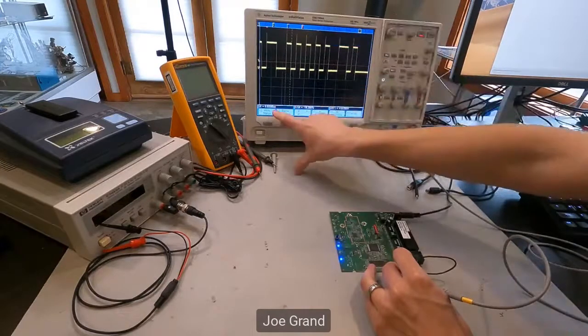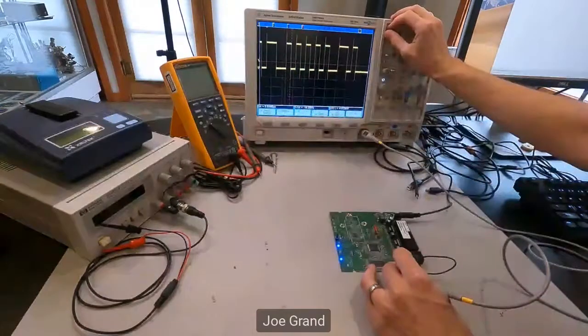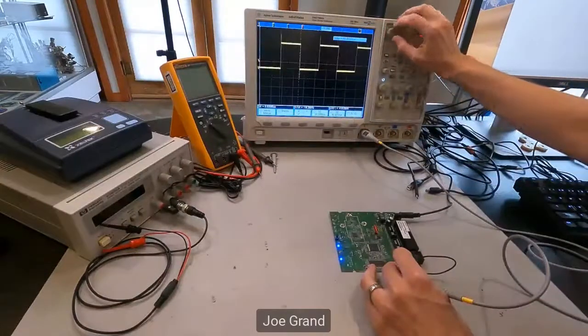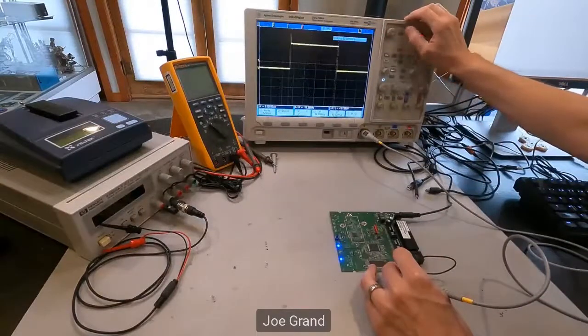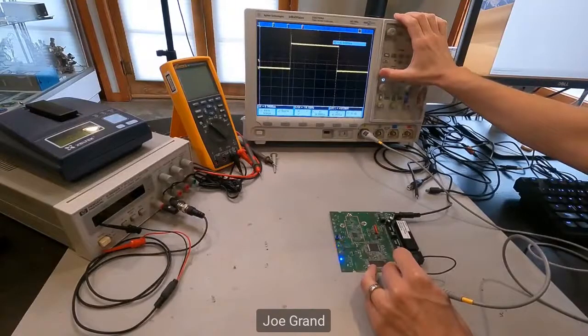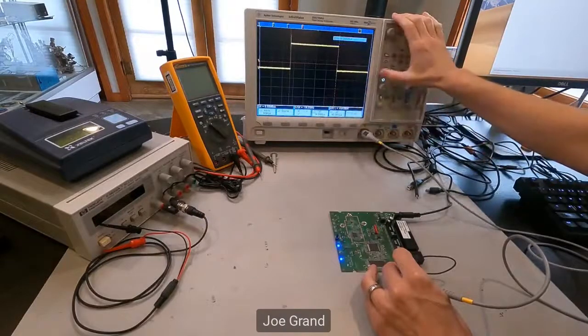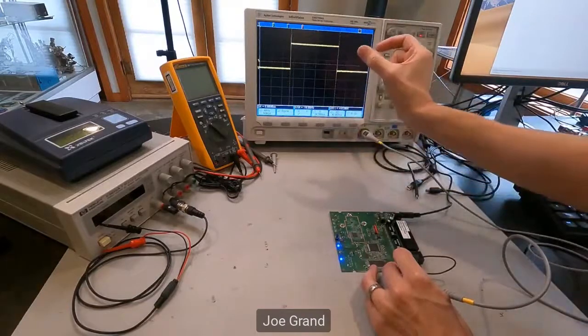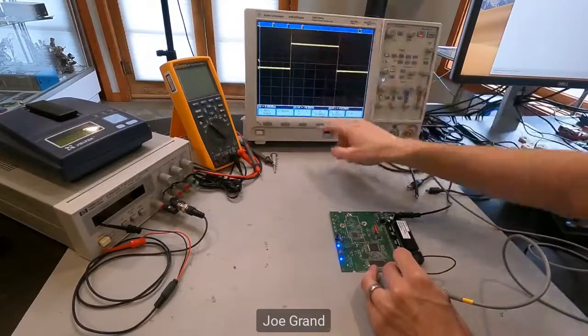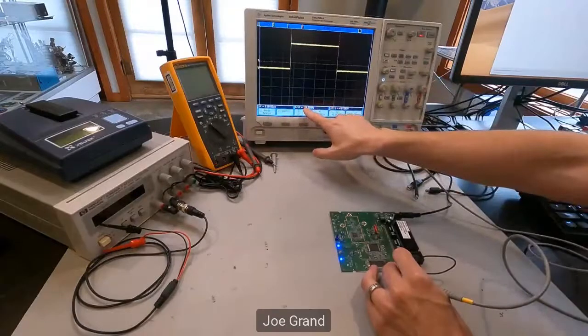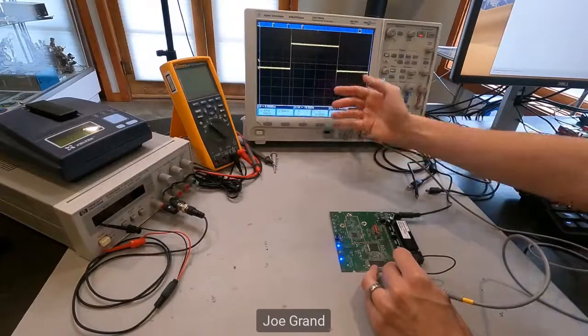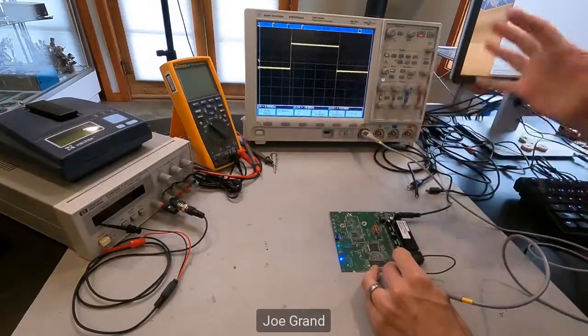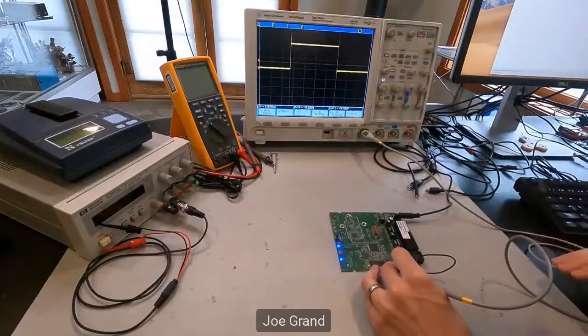So what do we see? So we have about 8.6 microseconds for the width, maybe a little bit less, kind of off here. Let's see. Yeah, 8.5 microseconds, which is the time it takes to send 1 bit from this system. If we invert that, it's 116.55 kilohertz, which would be a 115.2 kilobits per second UART data stream.